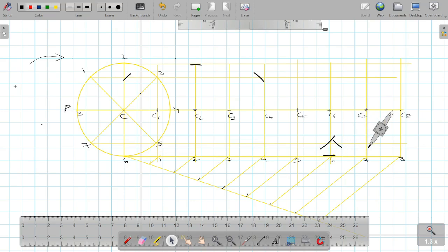Then next is shifting to projector 8 and again cutting on the left side only because P is moving up. So the projector for 8 is this one. So we'll make a cut at this particular location. Now we will give the names to all these points. So this is point P1, then this is point P2, P3. So this is P4. Then we have P5, P6, P7, and P8.